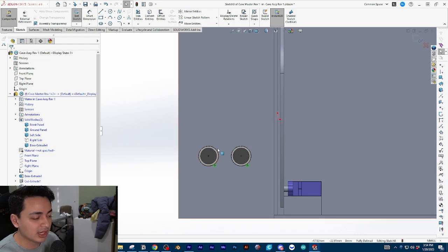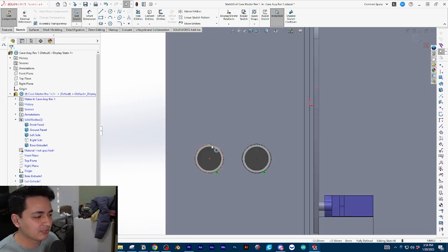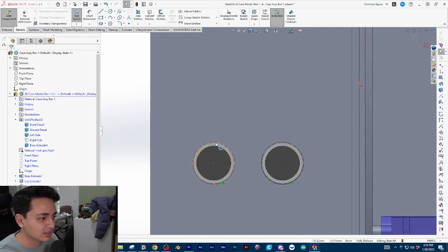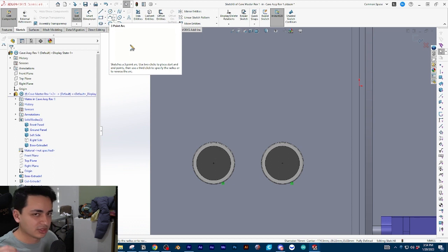So if you make a hole for a part to go through, you need a little bit of space outside of the diameter of. I'm not explaining this well. So let's say you have this circle, this ultrasonic sensor, right? And you need a hole so that you could push the ultrasonic sensor through. You're going to need a small amount of space between this outermost circle and the size of the actual hole so that it can fit through, right?